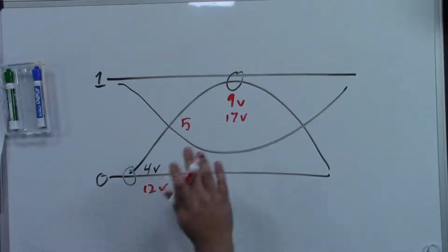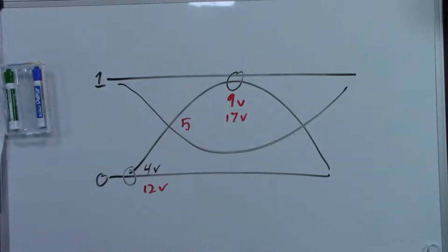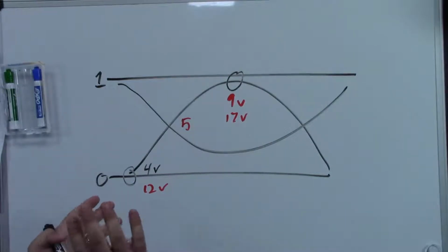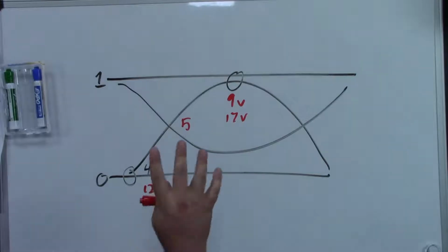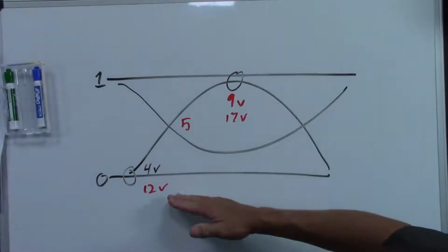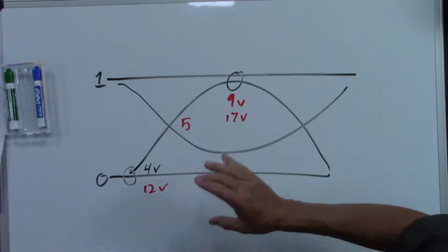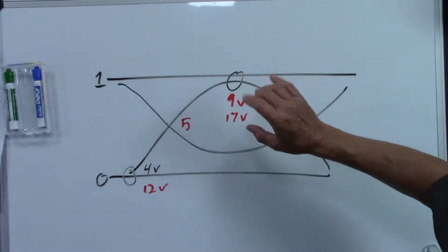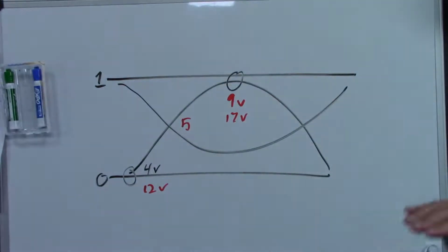Now, the data that's being transferred across those lines is still there, but now we are switching to a more powerful carrier. We can now have the power be sent down that same line because the voltages don't care. It's the difference that we look at. The differential. Exactly. That's why it's called differential voltage. And we can siphon off this voltage to run a device. Because all we need is that 5 volt swing to know if it's a 1 or a 0. Exactly. So it's just the baseline moving.